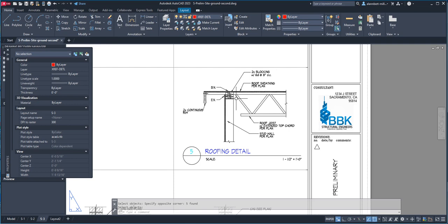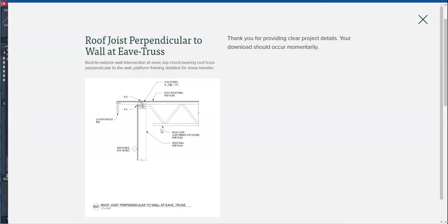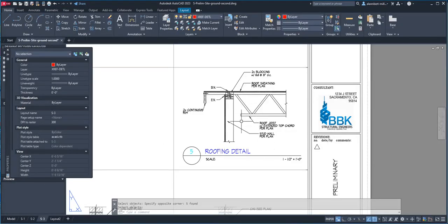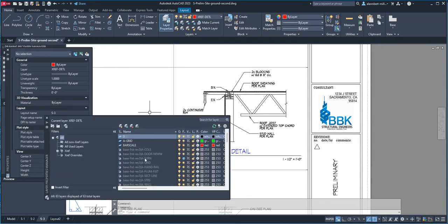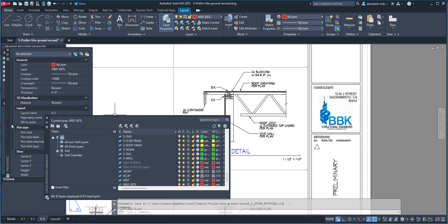Okay, so most of the details that you can get from manufacturers are drawn from AutoCAD itself. So when they created a PDF, it also created layers on the PDF. You would have your layers for your PDF here. Let's see here. The layers, Rev 2, first Rev. Oh, we said combine it to the one layer, and that's a block. So we didn't create the layers over here. Okay, so good thing we did that.